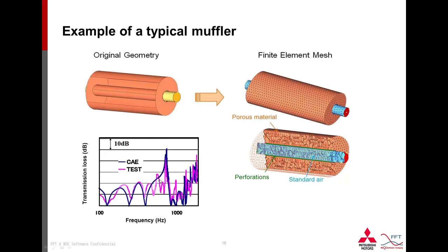And as frequency goes on, we have this complex pattern, which means we are going beyond the frequency range for plane wave propagation. We are starting to have complex waves propagating in the system, and this phenomenon can only be modeled using a 3D acoustic software like Actran.